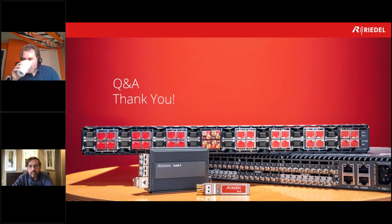Yeah, I know one of the manufacturers calls it break before make or make before break, right? Correct, some of them call it that. So we can do both. But again, it depends on how you use the 25 gig. If you use 2 UHD, we have to break before make, right? We don't have enough bandwidth in the 25 gig to have 3 UHD at the same time. So we'll break, but if you have, let's say, HD in there, we can do the make before break.